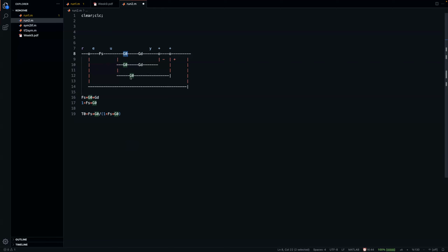Of course, these advantages, being simple to use and having the structure handle the delay part, come with a major disadvantage and drawback. It is dependent on the model. As with any model matching method, it mostly relies on the model of the system, and it is important to match the delay part exactly here. Otherwise, we will be in trouble, because ideally you want to see that this branch here, this difference here, is